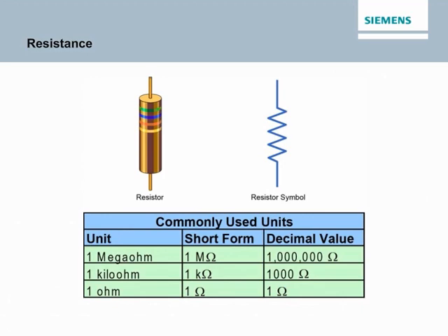The unit of measurement for resistance is ohms, symbolized by the Greek letter omega, which is the horseshoe shape in the accompanying graphic. Because 1 ohm is a small unit of resistance, kilo and mega are the metric unit prefixes most commonly used when quantifying ohms. While all circuit components have resistance, a resistor is a component manufactured to provide a specific resistance. Most resistors have color-coded bands that identify the amount of resistance. The accompanying diagram also shows the resistor symbol most often used in an electrical diagram.